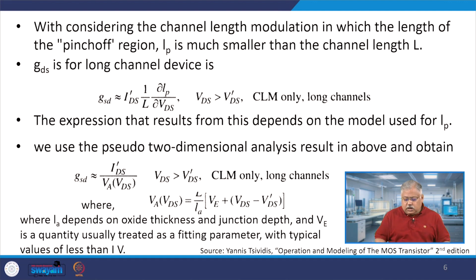Let me explain to you, and then I will come back to it. So, what happened was that when your channel lengths are very small and you have applied a drain bias here, which is say positive in nature, since you are reverse biasing it, the depletion region will actually be more towards the drain side, and therefore, the channel will pinch off much earlier than your source. So, the channel will finish here, which means that your effective channel length was actually this much, right, but you ended up having your channel length to be only this much.